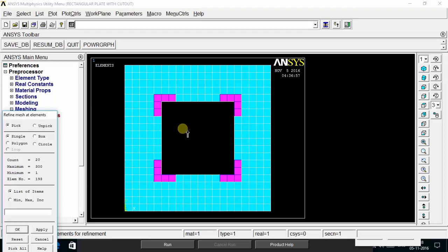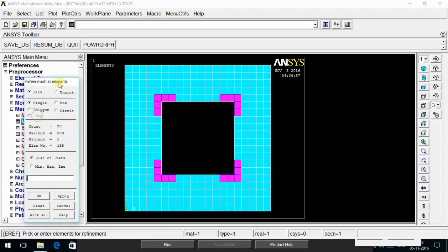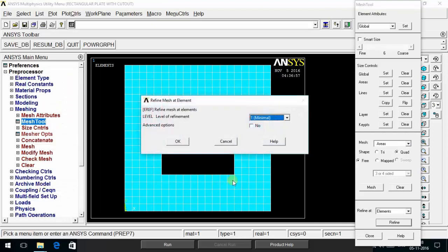Okay. Now by chance, if you have clicked somewhere here and now you need to deselect this, just right click so that the arrow changes its direction. Then come on this box, left click, that disappears. Then again right click. Okay. Hope you got that. Now let's click OK.